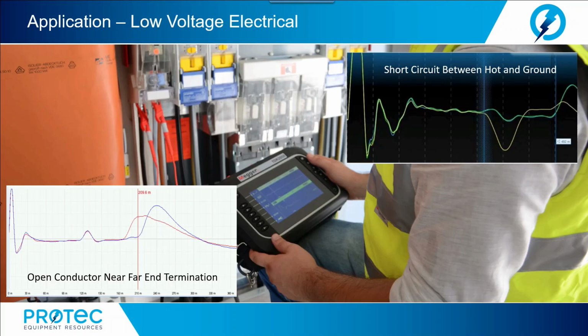Let's continue looking at low voltage electrical applications. Now, the best methods for fault locating on a low voltage circuit involves a good versus bad type of comparison. A healthy TDR trace produced by the complex network shows many reflections caused by the service connection, taps, and the ends of these cables. Now, even a gross fault down the network would be masked by the other features of the network. In many cases, comparisons and differential techniques are the only options.